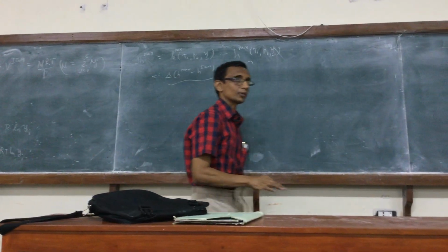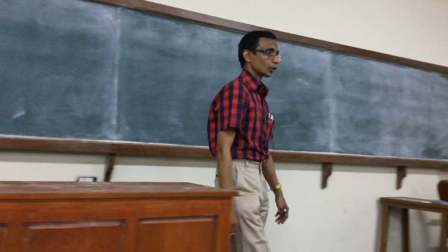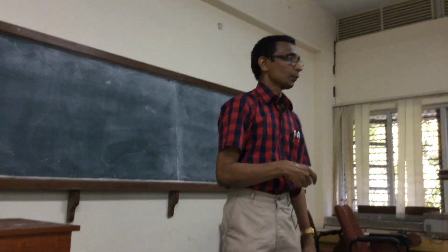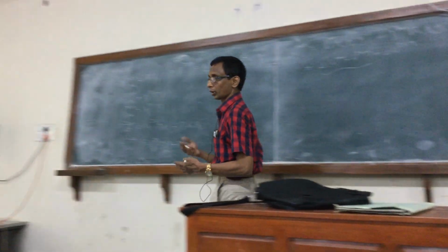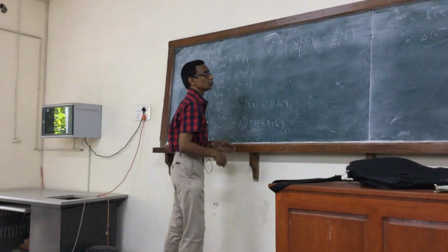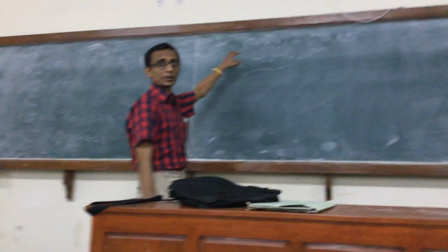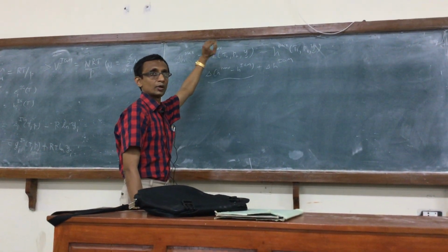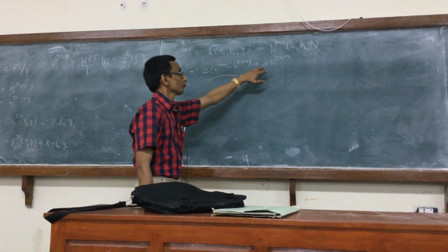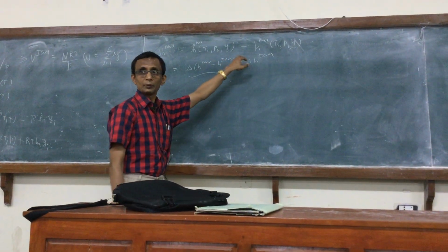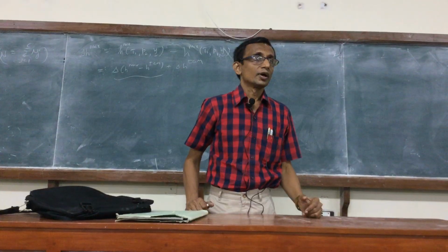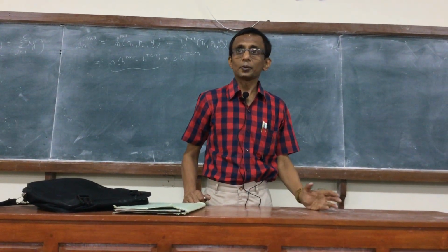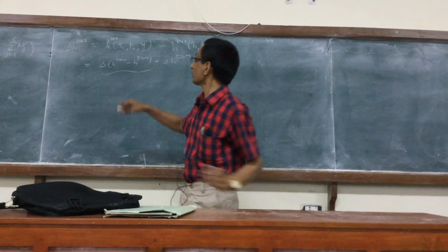This is almost identical to the calculations for the pure component, except that you have to calculate the mixture parameters of the equation of state for the particular mixture using some mixing rule, any mixing rule that is available to use. So that will depend on the mixing rule also, how the calculation goes. We will do that with a simple problem. But now we'll take up how to calculate the change in any property, the corresponding change for the ideal gas mixture between the same states.